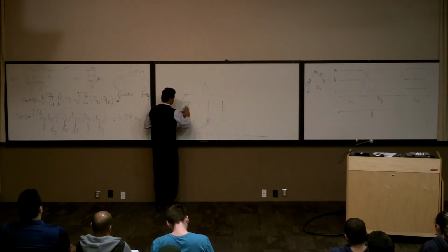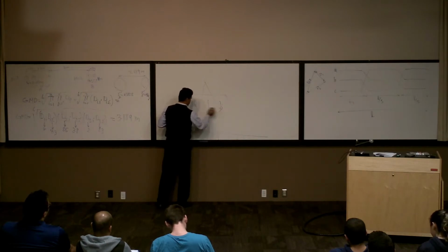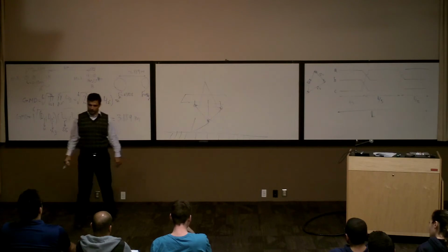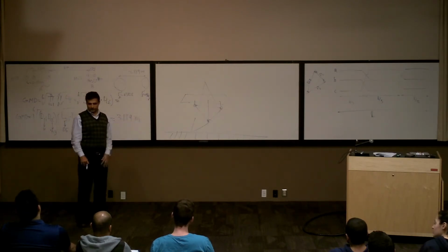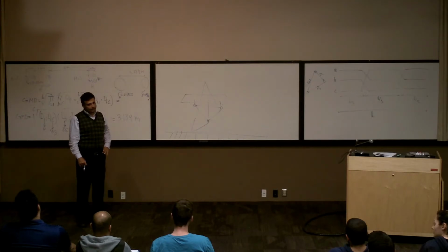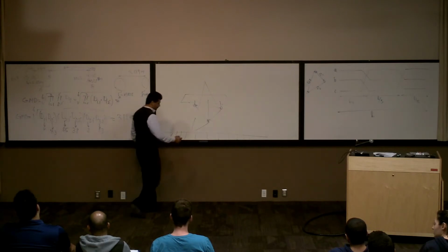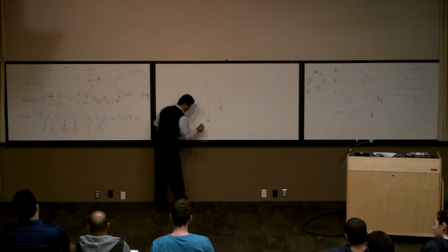This is still not good. I can bring this one a little bit this way, and this one a little bit this way, to make these three equal. Right? This is what you're saying. We don't need to transpose it anymore. But what is the problem with this? Can somebody tell me? Essentially, the distance from each conductor to the ground is not the same. Is that consistent?